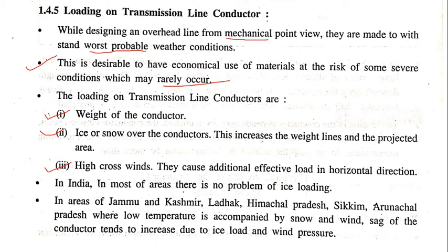So in India, in most areas there is no problem of ice loading, except Jammu and Kashmir, Ladakh, Himachal Pradesh, Sikkim. Okay, let's see this: in the areas of Jammu, Kashmir, Ladakh, Himachal Pradesh, Sikkim, Arunachal Pradesh, where low temperature is accompanied by snow and wind, the sag of the conductor tends to increase due to the ice load and wind pressure. So sag is going to increase in this type of situation.